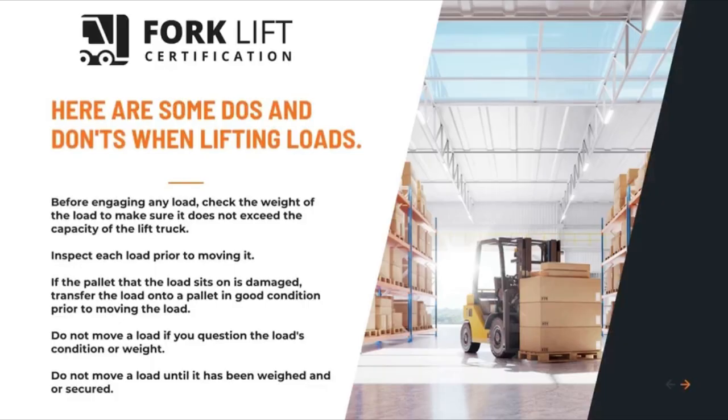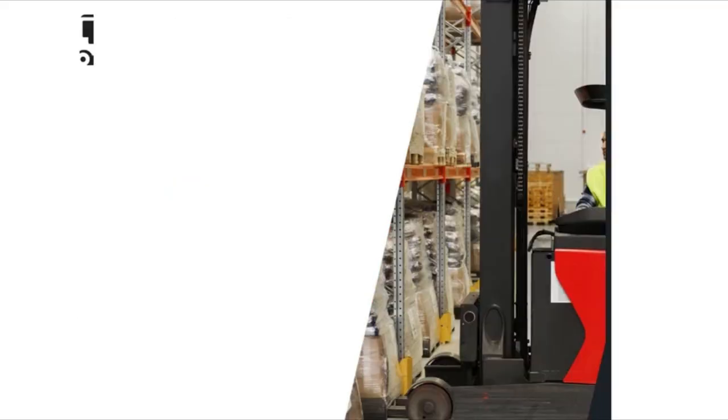Before engaging any load, check the weight of the load to make sure it does not exceed the capacity of the lift truck. Inspect each load prior to moving it. If the pallet that the load sits on is damaged, transfer the load onto a pallet in good condition prior to moving it. Do not move a load if you question the load's condition or weight. Do not move a load until it has been weighed and or secured.